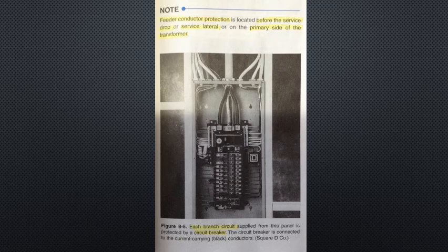Ungrounded hot circuit conductors have overcurrent protection at the point of supply. Overcurrent devices must be readily accessible, free from physical damage, installed in an enclosure or otherwise protected, and away from flammable material. The movable parts of an overcurrent device, such as handles or power actuated mechanisms, are guarded to protect personnel. Typically, branch circuit overcurrent devices are located at the power panel.